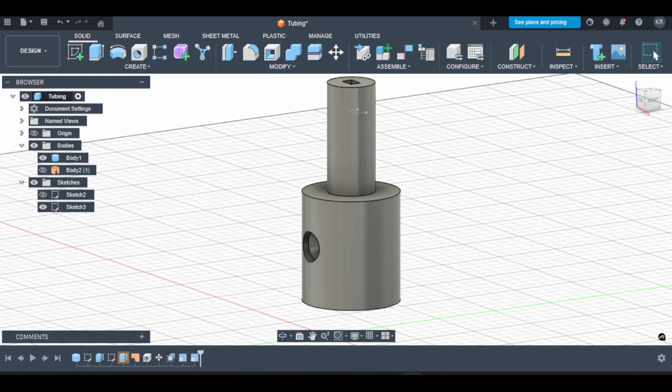If you're working on an assembly, make sure all components are in the correct position and fully constrained as intended for real-life use. It's a good idea to save a version before you begin, since simulation settings live with your design file and you'll likely want to iterate.